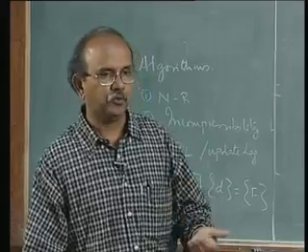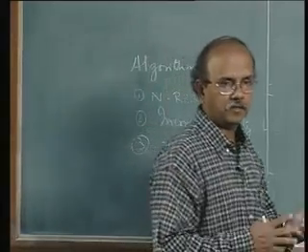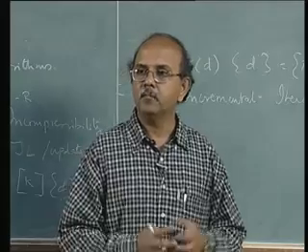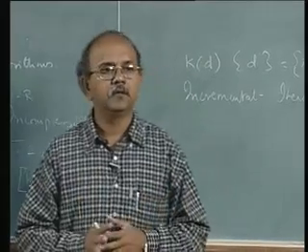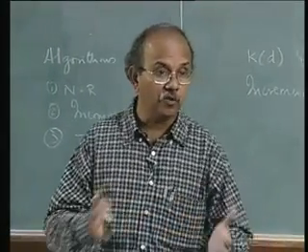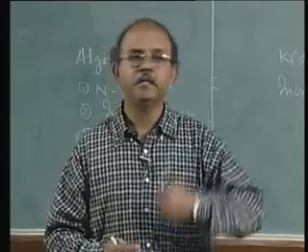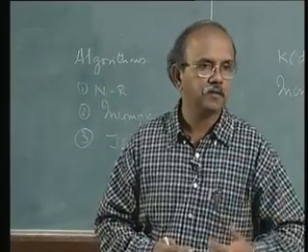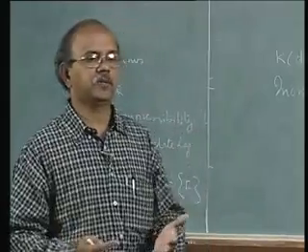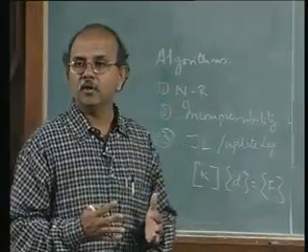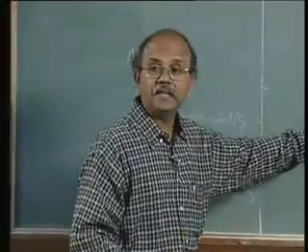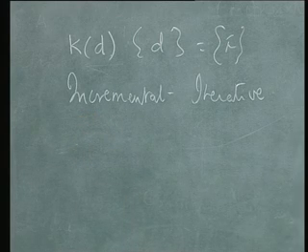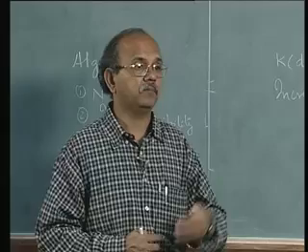I will apply 100 newtons initially, make the body or component come to equilibrium with that load, then increase that load maybe to 200 or 300, then make the body again come to equilibrium, and so on. So this is what we mean by an incremental approach, where I keep incrementing the load.